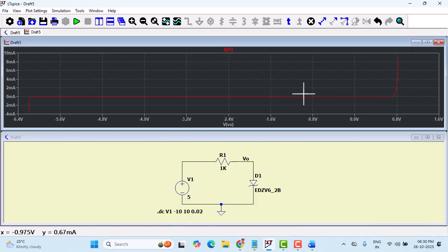Probably when you go to the laboratory and construct a circuit like this, and have a voltage measuring instrument across this and measure the current flowing through this, if you plot, you may not get an exact curve like this. There will be deviations in the practical graph of voltage-current characteristics, but this is accurate. Generally, the cut-in or threshold voltage of a diode will be 0.7 to 0.75. That range depends on the type of diode.